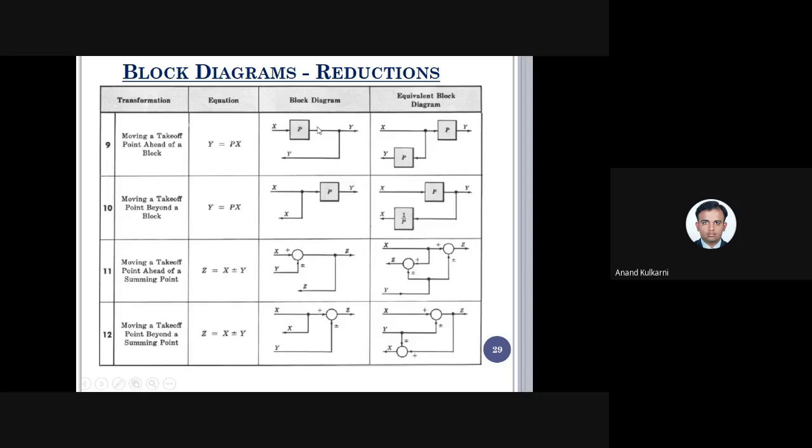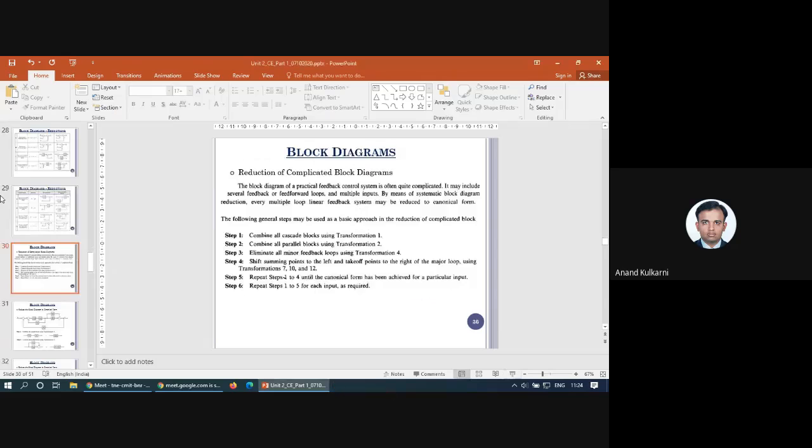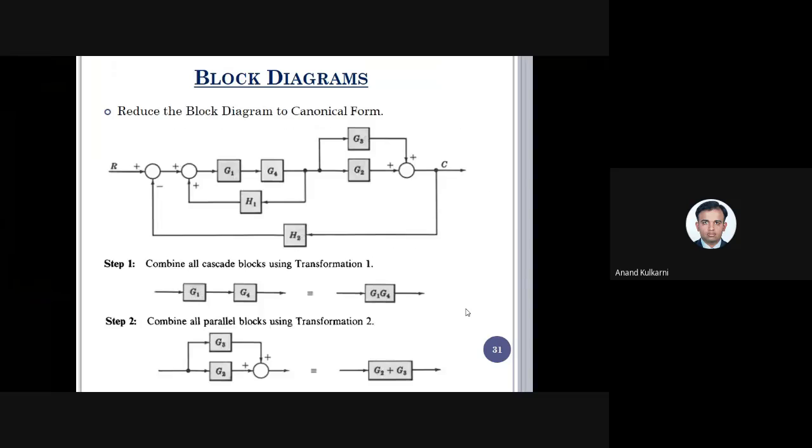Then similarly, when we are moving the takeoff point ahead of the block, we multiply, and if we are moving the takeoff point behind the block, we divide. So with this, whatever basic rules have been discussed, we'll be solving the problems now.